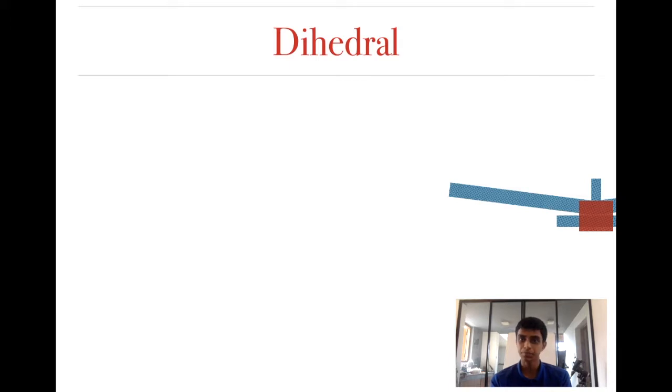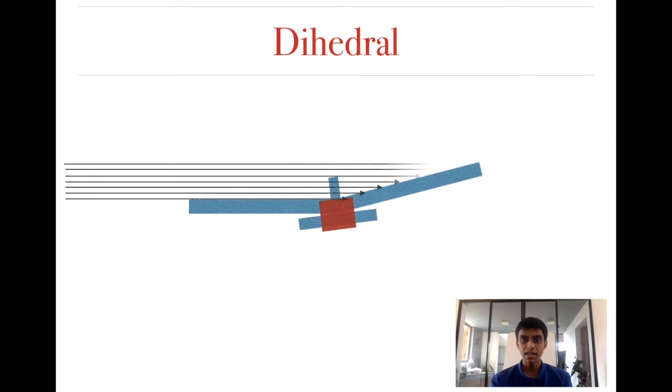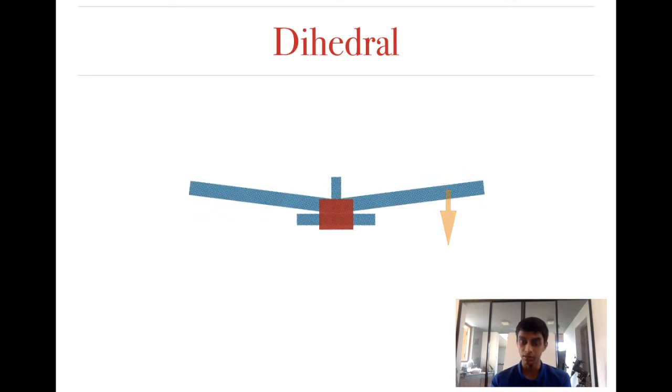This is how it works. Say that the plane accidentally banks towards one edge, right? If it banks, this means that the plane will start moving to the left direction, basically your left direction. In this case, wind will start coming and hit on the right hand side of the wing, your right hand side, okay? This will mean that there will be a force acting on that wing because all of that airflow is coming and hitting on it. And this will correct the airplane. So that's the function of the dihedral.